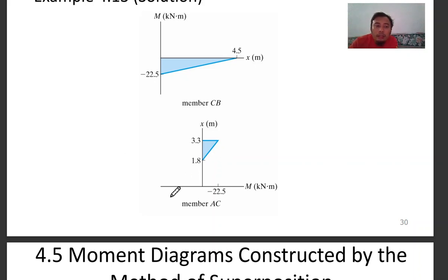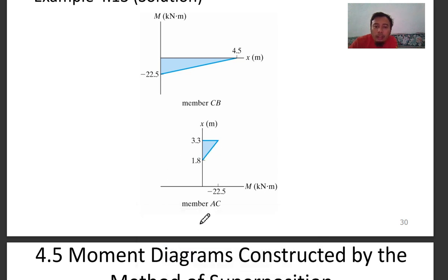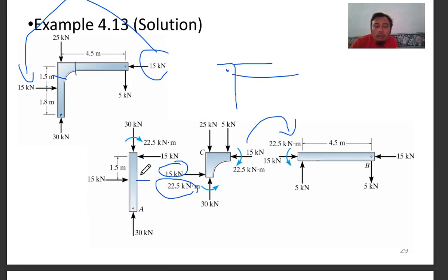Actually, this is a bending moment. There's a question stated that you need to find the bending moment. Basically the shear force diagram will be square at this, and for this one, square, because when you draw your shear force diagram, it will be negative 15, then go upward back to 15, and then you achieve equilibrium.